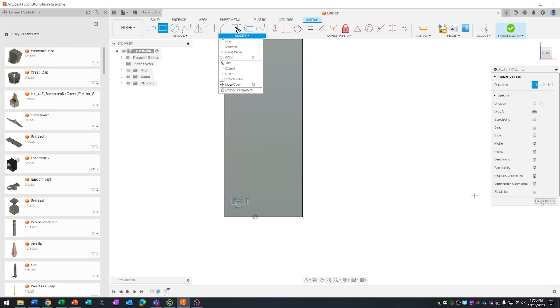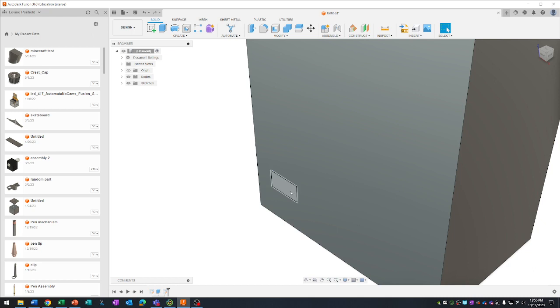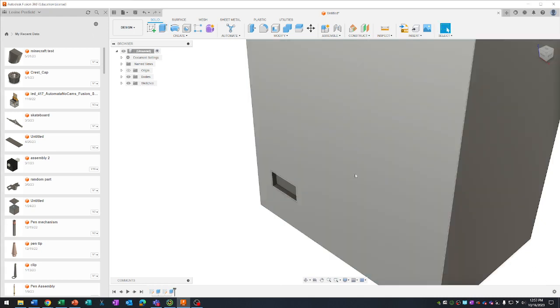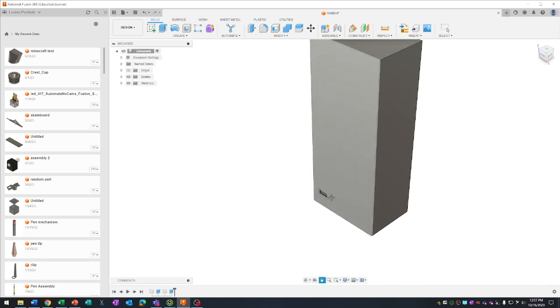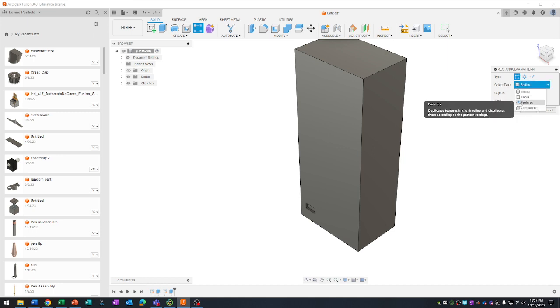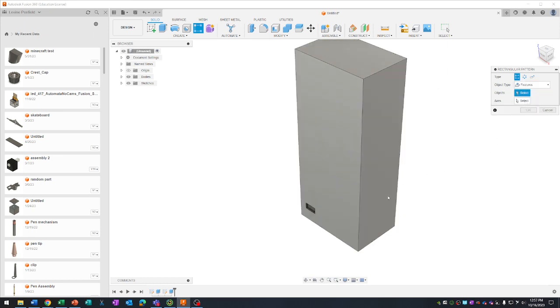So moving on here, I'll finish my sketch. I'll extrude this shape just to give my window a little bit of depth, and then I'm going to copy that, now cut extrusion for the face of the building. So I will rectangular pattern this up around the building, but I need to change the object type. The object is called a feature. We've done a little bit with faces for texturing; bodies and components we'll get into later. So feature, select the object, I'll just select that cut.